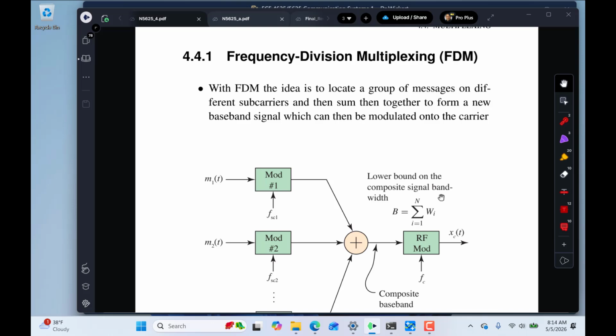And then when we evolved that into generation 2, we had frequency division multiple access with time division multiple access. In other words, everybody gets a channel, but they have to share it with many other people, 6 other people on one of the standards that came around. But then everybody gets a slot, a time slot in addition to a frequency slot.